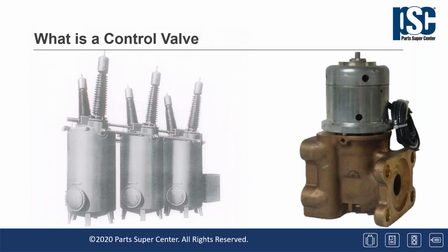The control valve, a photo of which is located on the right-hand side of this slide, is an integral part of an oil circuit breaker. It's the device that initiates the flow of air from the air receiver or tank in the mechanism to the piston that does the work of moving the linkage to close the breaker. You will often hear it described as a closing valve. It contains a coil that operates the pilot armature within the valve, and that coil is often referred to as a closing coil. You can see that the valve is bolted up to plumbing within the mechanism in the photograph.